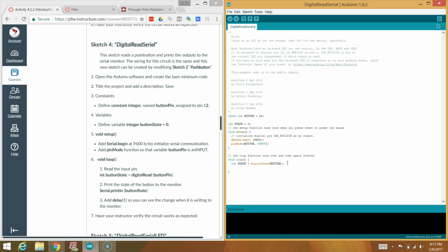Then we want to write this Serial.println, and button state. We're just going to say state. That's what we've named it. And then add a delay. It says a delay of 1. I'm going to lower that delay down to, let's say, about a quarter of a second.